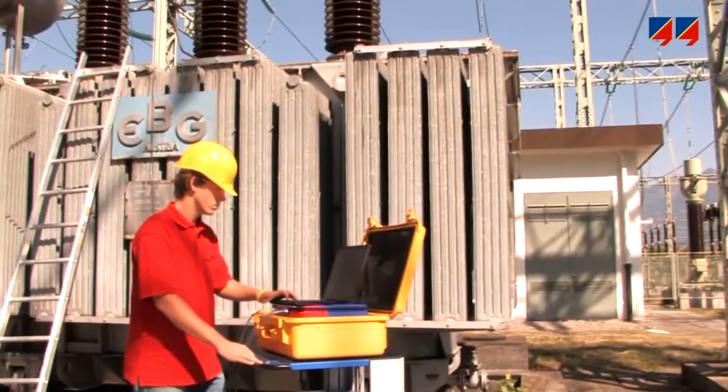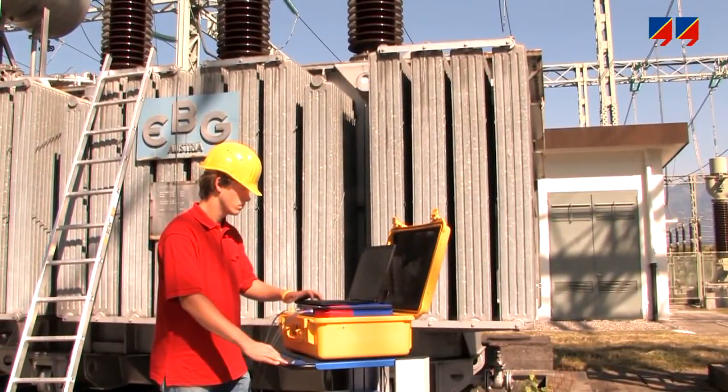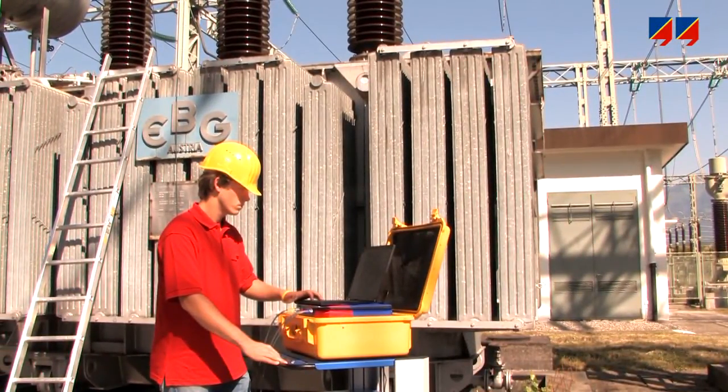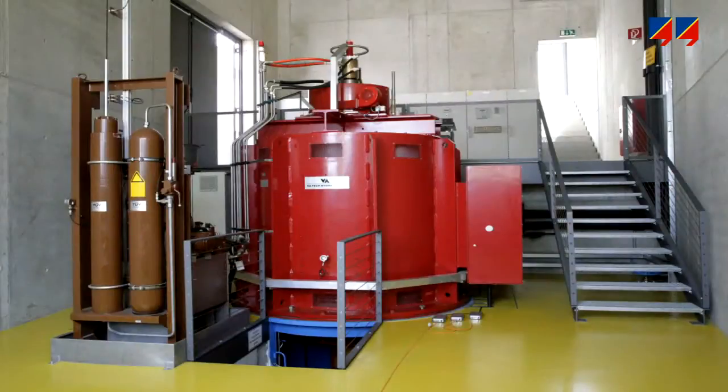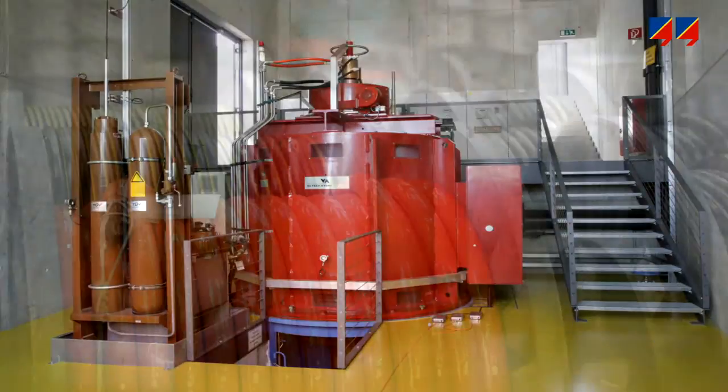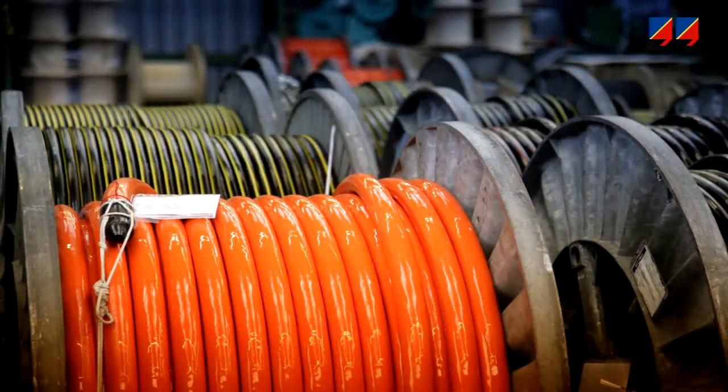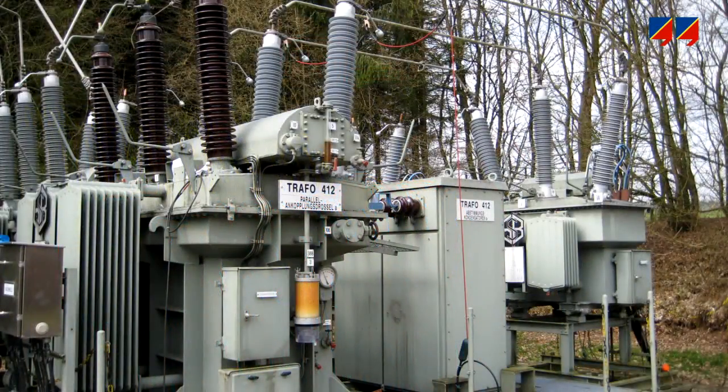Dielectric response methods allow the direct analysis of the solid insulation of the transformer. They can also be utilized for the evaluation of bushings and the insulation properties of motors, generators, and paper-insulated oil-filled cables. But first, we should consider what leads to the degradation of a power transformer.